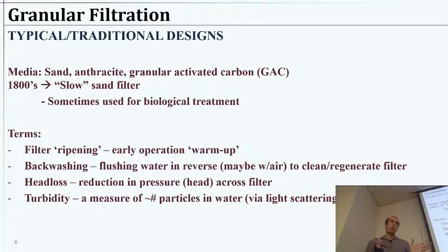And when we do it that slowly, we can actually have biological processes helping too. Helping or perhaps hurting depending on how we look at it. But if we had dirty water, microbes might be able to eat some of the junk that's in there and convert it to stuff that's just going to be left in that sand plus bacterial mass. Nowadays, we send water in much quicker. We're not waiting long enough for biology to happen. Of course, there's probably going to be microbes on the sand or the grains, but that's not anything that we are designing for or intending to use.